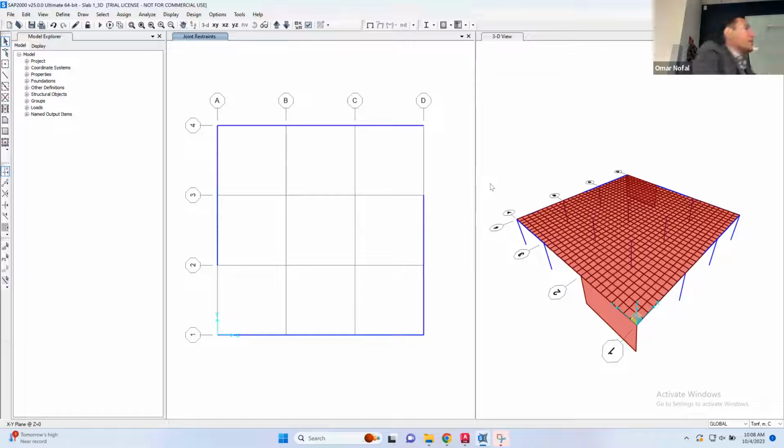So I need you to distinguish between what we did a few minutes ago. What we did in 2D models: the slab system is supported by hinges in 2D. And we decided a few minutes ago that we need to move this model from 2D to 3D. So we are going to remove all these hinges and make columns, and these columns are going to be the support. Okay, so I remove the hinges from up there, and I'm going to go to the floor down and put hinges or put fixation or whatever I want.